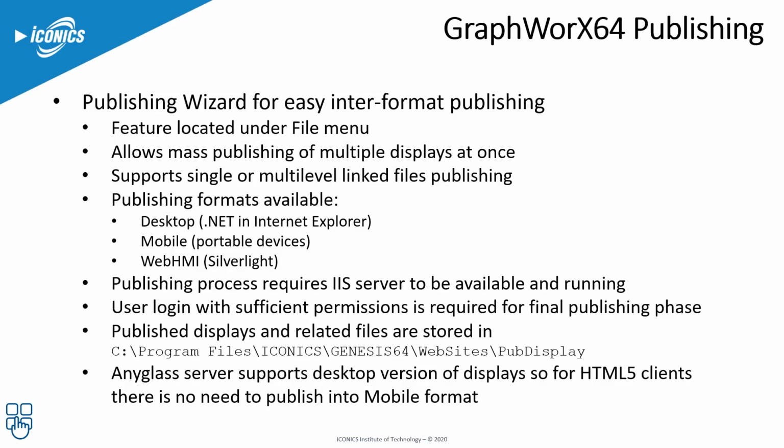For simplifying the publish process, there is a publishing wizard available directly in GraphWorX64 under the File menu. The wizard supports processing of multiple displays at once and allows publishing into different formats, for example, desktop WebHMI, mobile platform, and for legacy clients, also Silverlight format. All of those formats can be created and published in one shot.